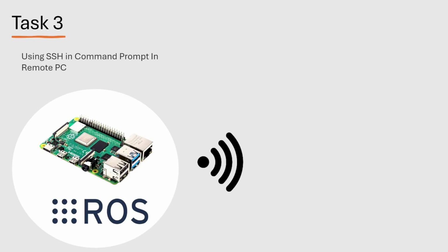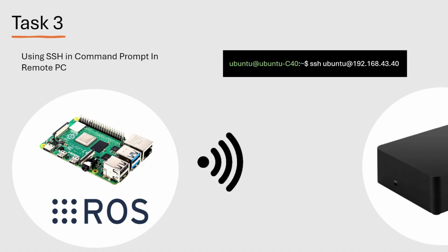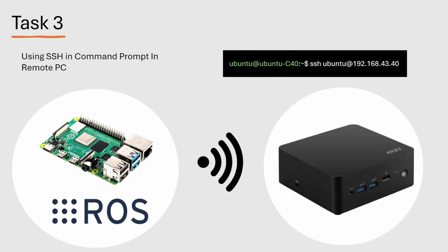We start by connecting to the robot over a network connection using SSH, allowing us to operate it remotely through the command line. Once logged in, we launch the Bring Up package responsible for activating all essential systems: motor drivers, the LiDAR scanner, the IMU, and other embedded controllers. During this step, we monitored data streams to ensure everything worked properly.